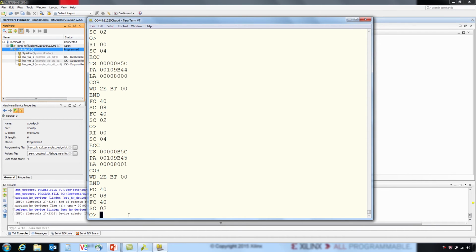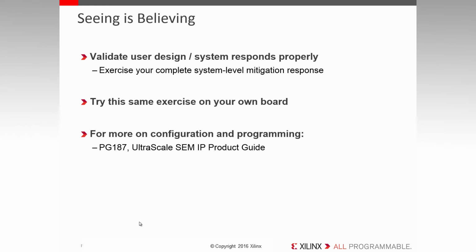What we just covered here represents about 99.9% of the SEU you'll ever encounter in UltraScale+ devices. The point of integration testing is not to relentlessly pound on the system, but to answer a critical question. Is the system responding as designed to the event reports? Answering this question is easy with the error injection capability of the UltraScale+ SEM IP. Now you've seen UltraScale+ SEU solution integration test is easy. I hope that what we just finished makes you want to try it.